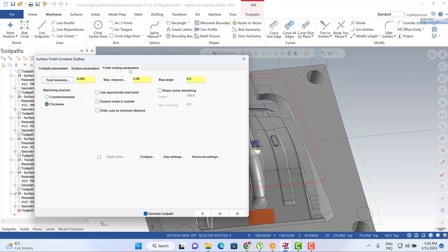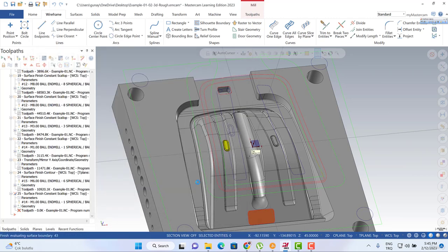If you intend to focus on that toolpath, actually you can turn to here and you can easily organize a different color, and then you can easily select your face. So that's also possible to work this way, by changing the color, and you can also select your toolpath by using the color options, as you can see here.